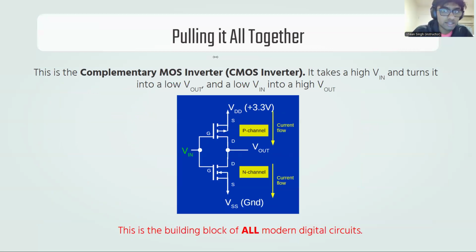We call this the CMOS inverter. Complementary, that's what the C stands for because it has a P and an N. They're complementary to each other. MOS because they use metal oxide semiconductor devices. And inverter because it inverts the V in. This is the building block. I cannot stress enough, this is the most important transistor circuit that you can write down.